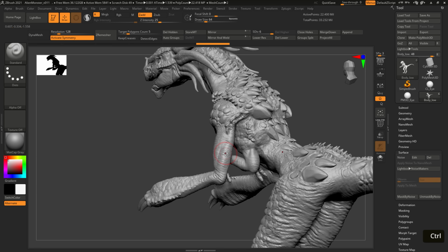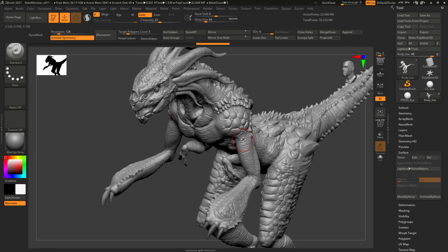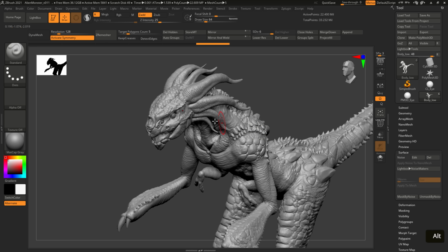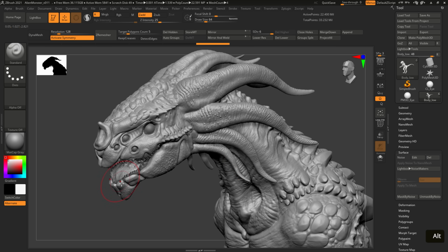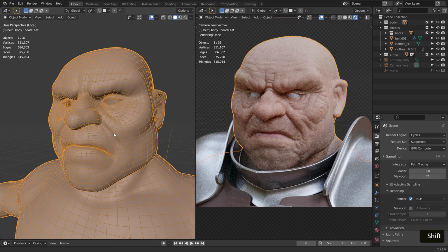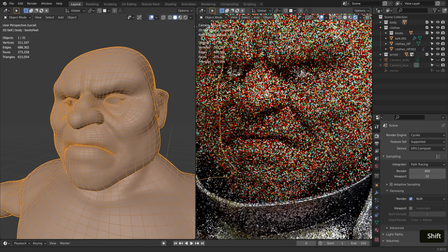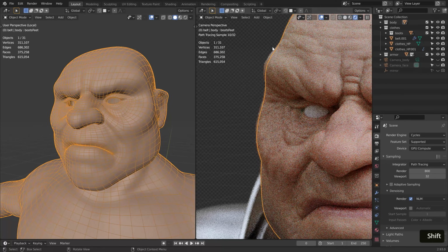That means that if you baked the displacement in a single UV tile, none of the sculpted detail will be visible due to the lack of resolution. So apart from color textures and maps, UDIMs can be helpful to display actual geometry detail, which you need to transfer back to your low poly model.